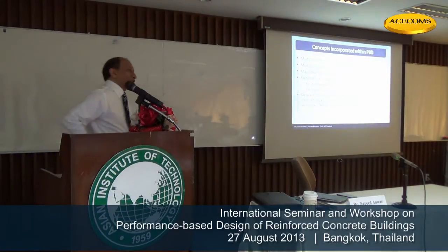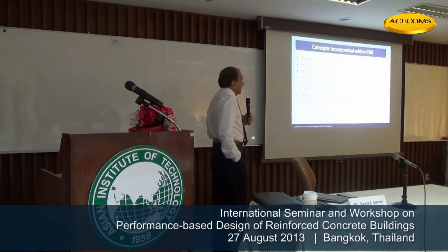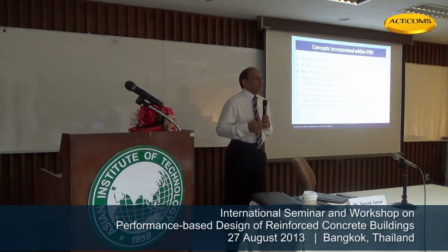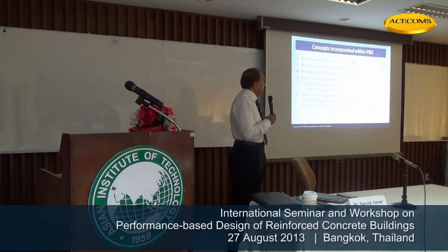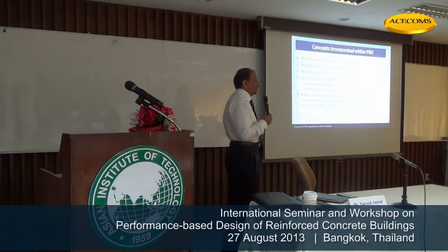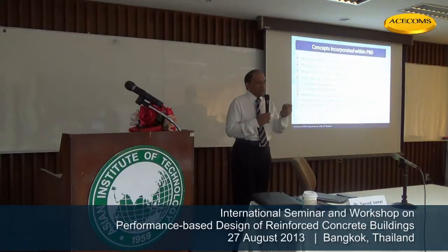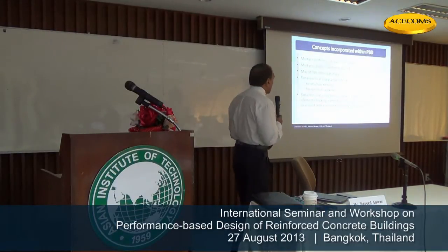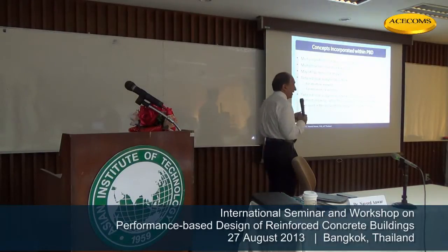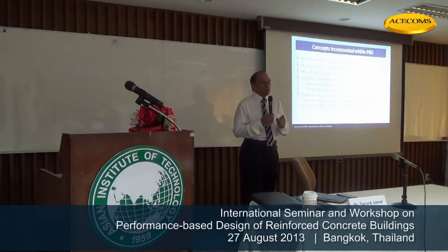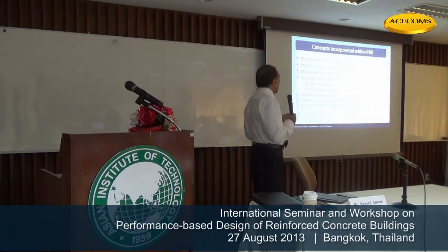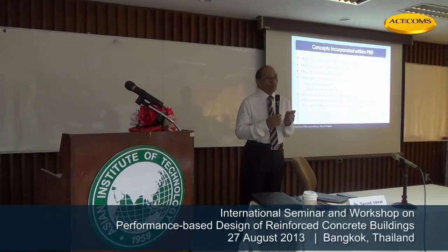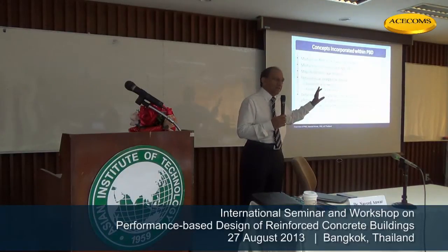So we know why we should do performance-based design. Now the thing is, what are the basic components of a performance-based design? First of all, multiple performance levels are checked. So we can check the performance at multiple levels, not just one level, explicitly. Number two, multiple seismic events are applied. So hazard levels could be different also. We check them explicitly. May utilize nonlinear analysis. Actually, I should say must utilize nonlinear analysis.